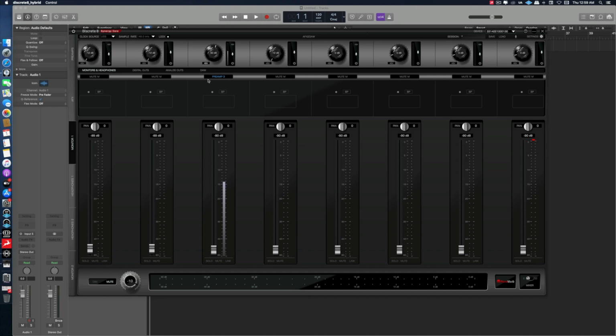We have selected preamp 3 in the drop down list of mixer channel 3. So if I want to monitor it directly onto the monitor, so this is the monitor, I can raise this. It will be sent through the monitors. But right now we don't need to do this. And on the headphones, you can see that I have selected the preamp 3 and I have raised the faders. You have to remember my previous word. There is no different selections for different mixers. The selection of the mixer channels are same for all the 4 mixers. Only you can change the fader positions, solo, mute or link.